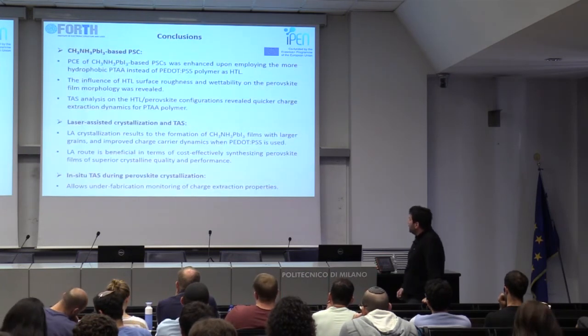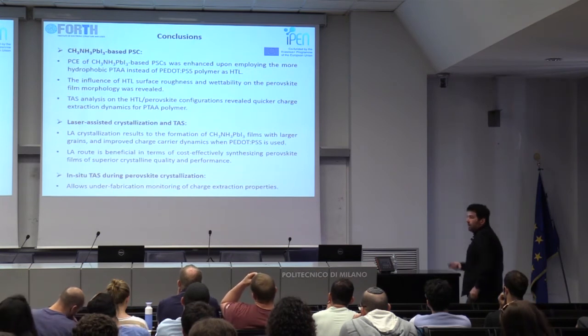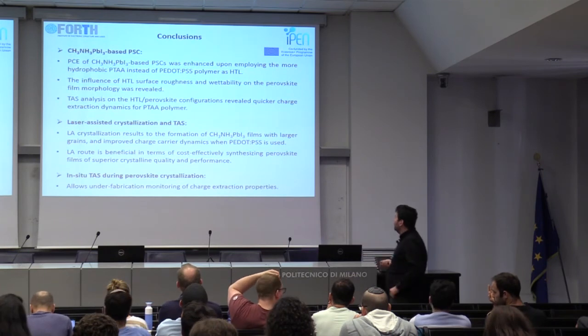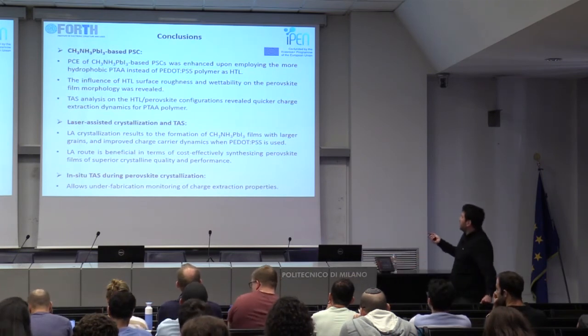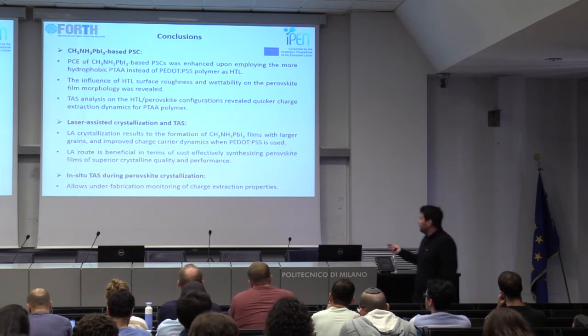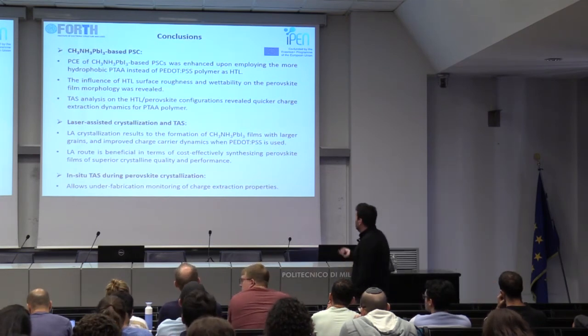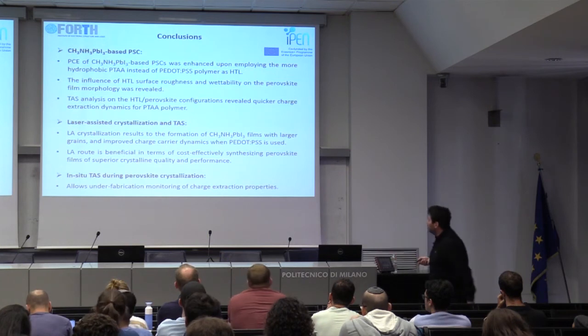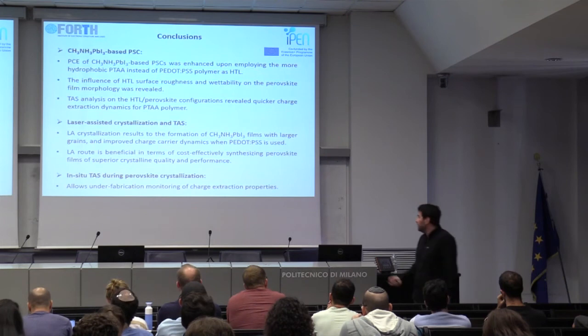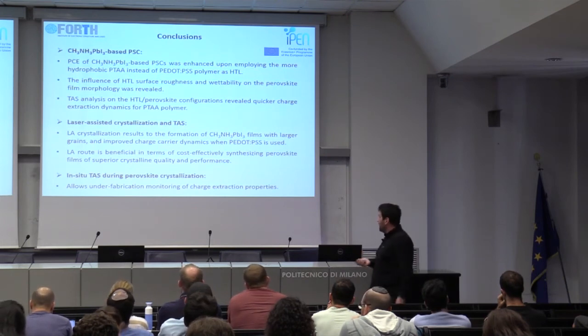And with this, I would like to conclude my talk. So for the perovskite solar cell devices, I hope that I demonstrated to you that by simply introducing the more hydrophobic polymer PTAA, we have better power conversion efficiency, and this was attributed to perovskite configurations with quicker charge extraction dynamics of the PTAA polymer.